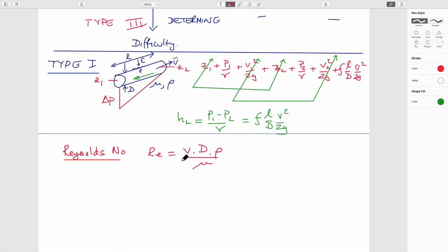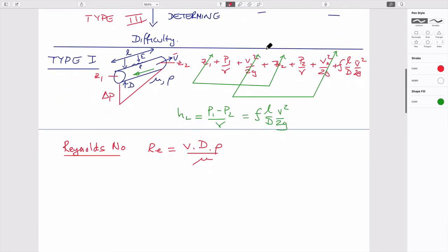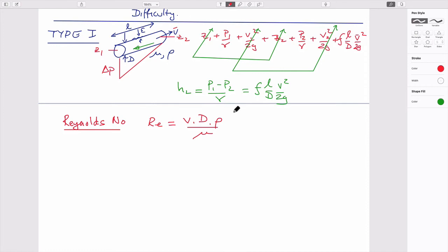And so the problem is that if we want to be able to do that, we need to know what the velocity is in the first place. So we have to kind of choose that. So since we want to maybe do this for both laminar and turbulent, let's calculate what Reynolds number is as a function of velocity. So keep velocity outside. Diameter, let's use 10⁻² meters. That's a centimeter, a little less than half an inch.